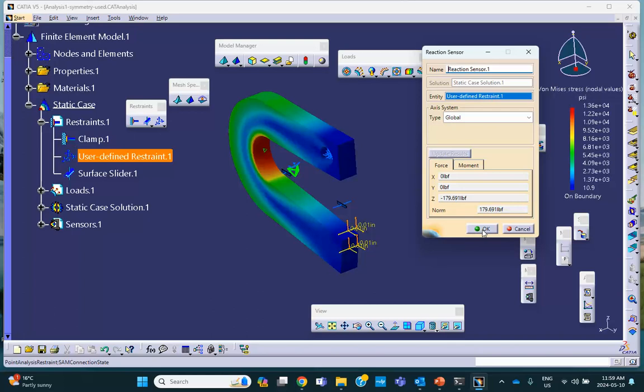So if you're asked on the test to use as many planes of symmetry as necessary, first of all, you use half of it, just like I did, you split this. And then at the end, if it asks you how much force is needed to create this deformation, don't put this number down. Multiply it by 2 and write the answer there, because double this is what is actually needed to inflict that deformation. So be careful, because I'm going to ask you in a particular problem how much force is needed to do something. You have to go through this motion.